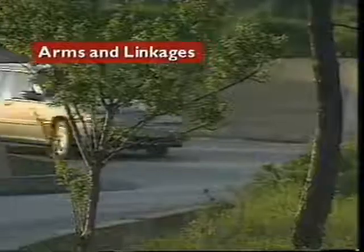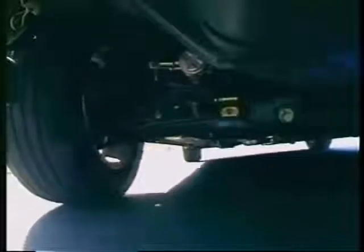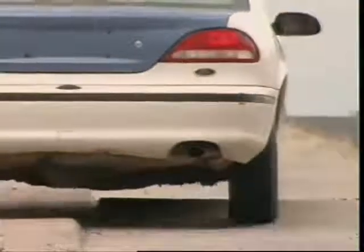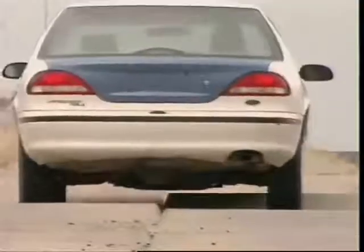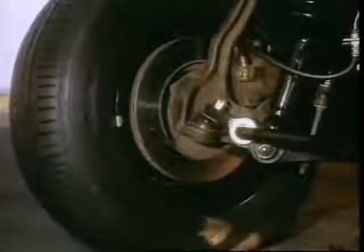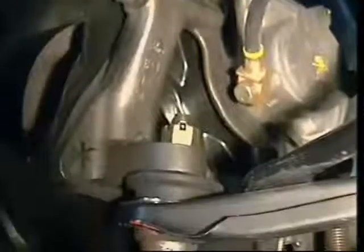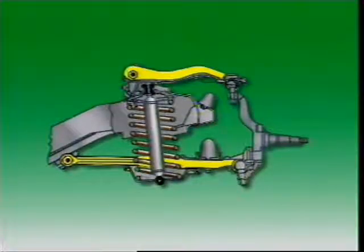This section examines suspension, steering arms, and linkages. The major components of the suspension system must be firmly located to withstand the forces that occur in normal operation. Control arms fasten a component like a rear axle assembly to the vehicle body, while allowing it to move as it needs to. Similarly with a steering knuckle. The arms must be strong enough to withstand the forces due to normal operation, but light enough to minimize the vehicle's unsprung mass. The front suspension can have 1 or 2 control arms.